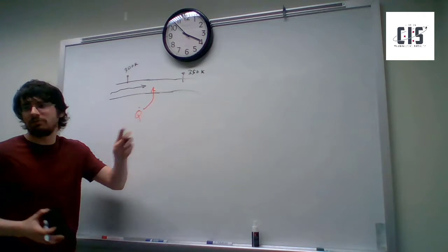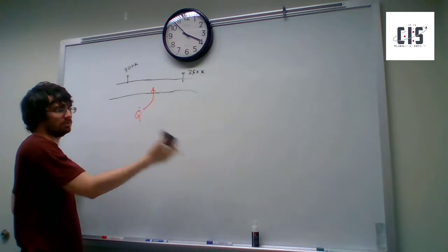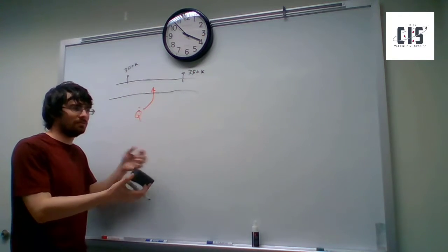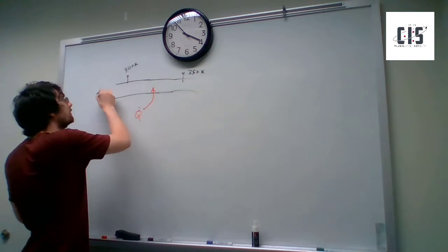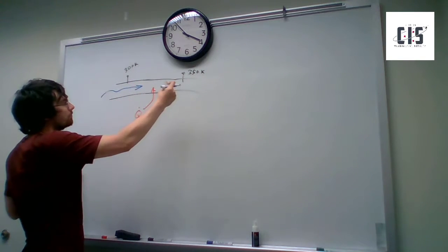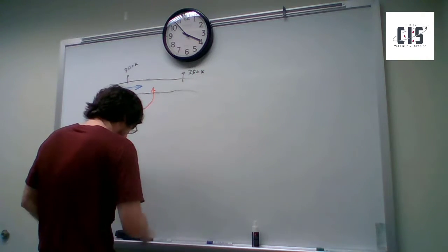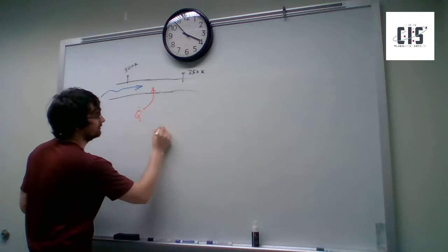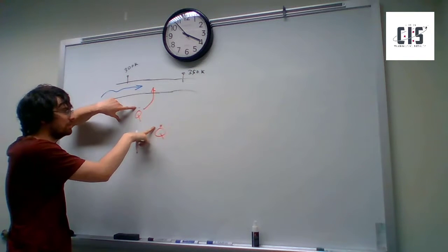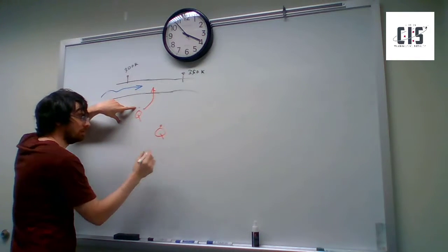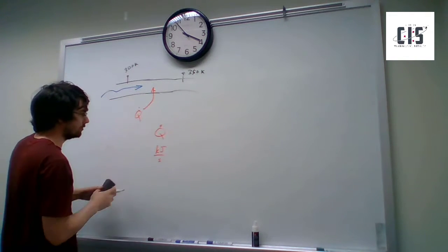Because it's a continuous process, so it's not going to be just kilojoules. If this process is going for 1 second, then it's considerably less mass than if it's a process going for 24 hours a day. Yeah, so, fluid going through a pipe, you need to heat it up by adding heat. So, for that, we just use dots. So, heat transfer rate. Whenever you see a dot, it usually means rate. So, in this case, kilojoules per second. That's important. So it's just a rate.